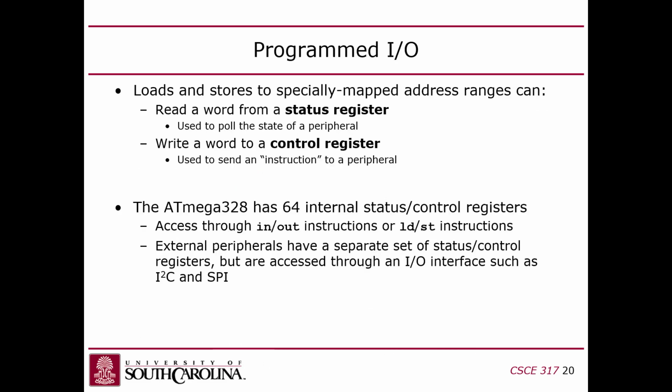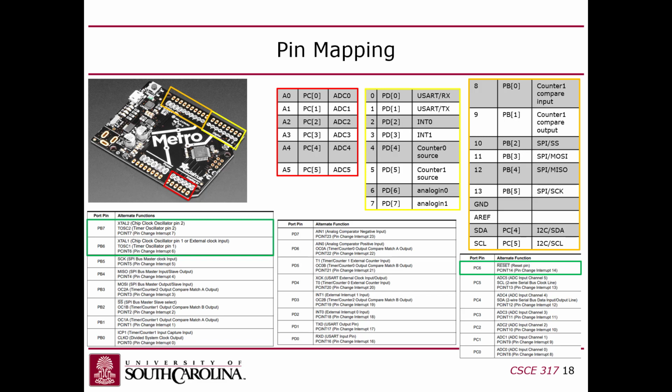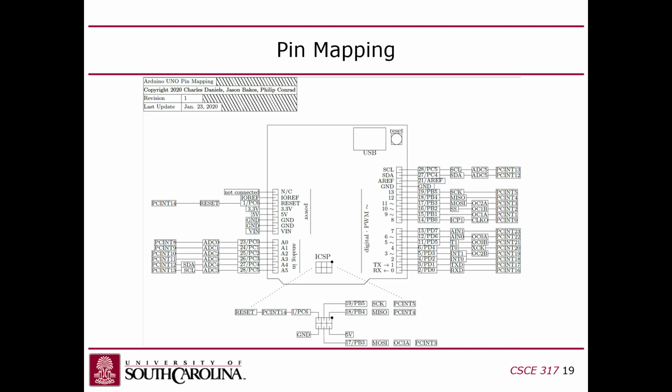Now on input, on the other hand, I don't know, maybe this is too far in the weeds, but if you were receiving data on the hardware UART and you were treating pin 0 of port D as an input, you could still read it, so you would be reading whatever the UART hardware was doing. You could have the software read it. I don't know why you'd want to do that, but you could in theory.